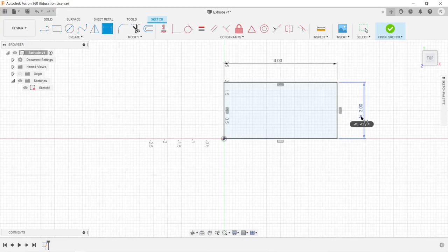It originates in a Microsoft standard for function, right? Back in the day with spreadsheets. So fx is short for function, and as a result of the function, it's 2 inches. All right, and then I can finish sketch. So I've dimensioned this rectangle. I have dimensioned using just putting in a number. I've also dimensioned by using a formula, okay?